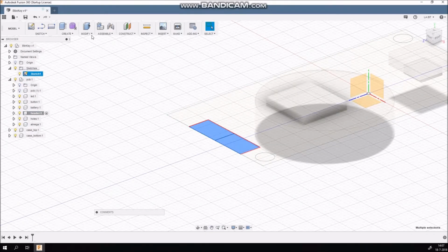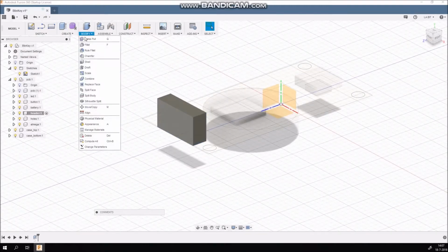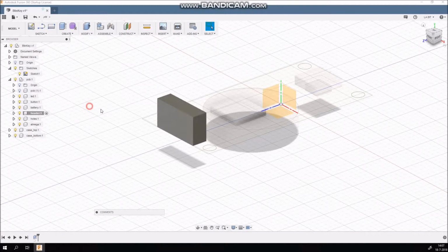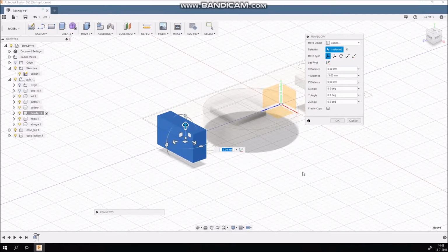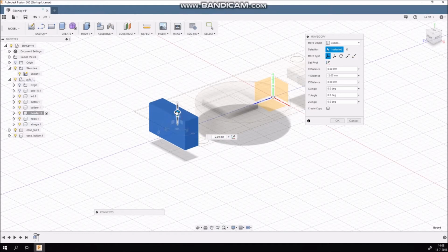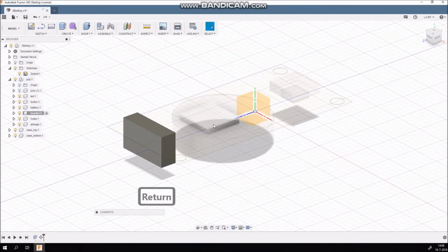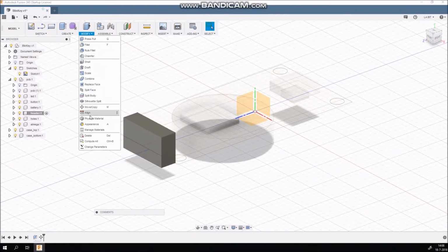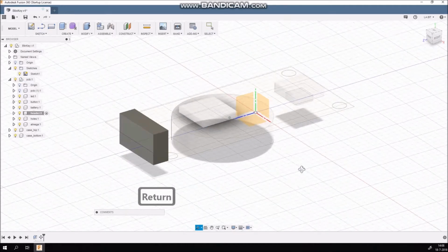But you don't mind, I have those special headers at the side of the board, so they're actually in the middle. So bring it down for about 2 mm, because the board is also 1 mm thick. Then select the microchip and bring it up 1 mm, so it's on top of the PCB. Do the same for the button.